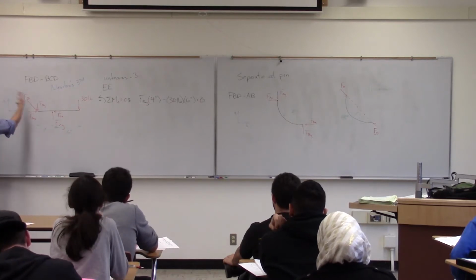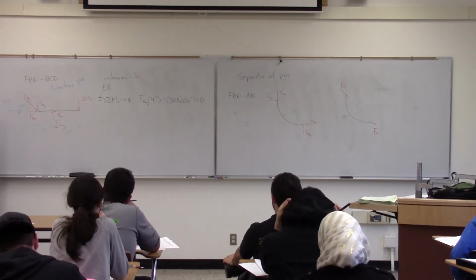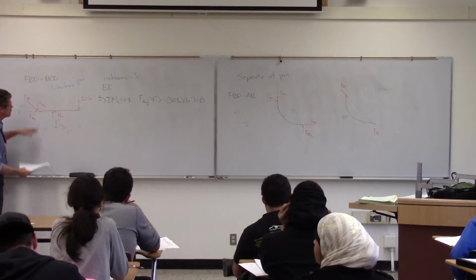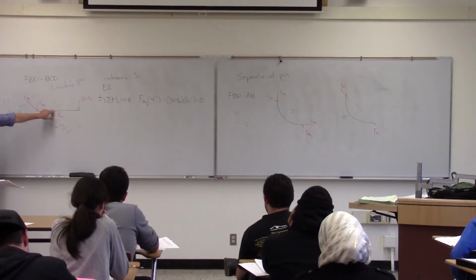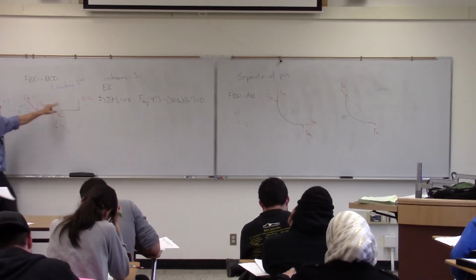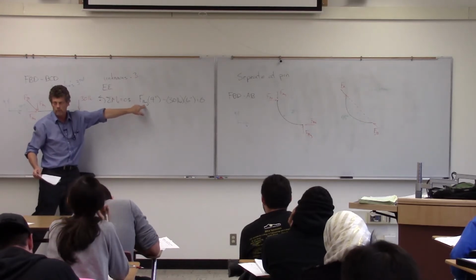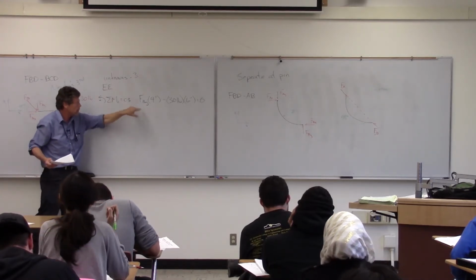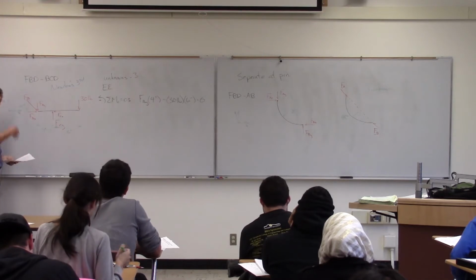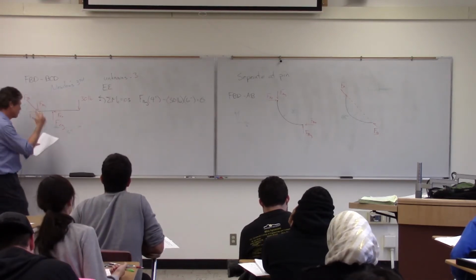What we're going to do is once we solve for that, we solve for FA. Okay. So going back there, I forgot my dimensions there, but we take the moment there. I'm solving just for the Y component there. So I can either solve for FBY or I can solve for FB times sine of 45 degrees, whatever you want to do.